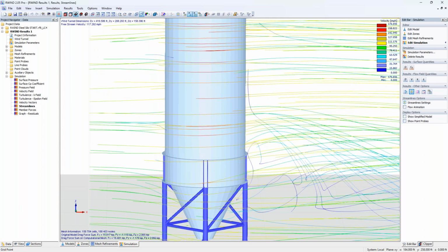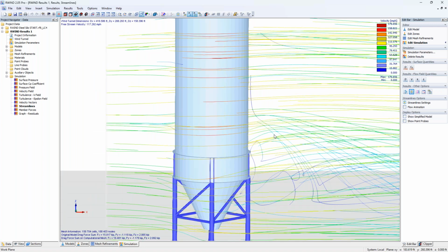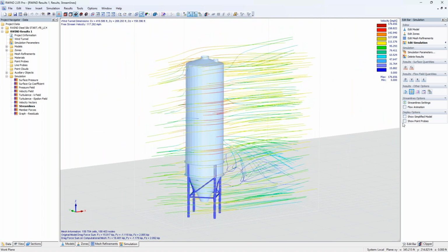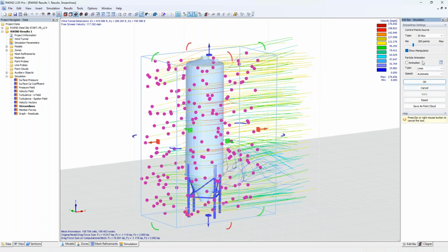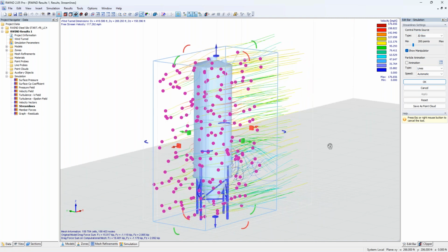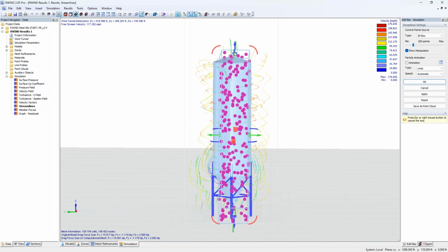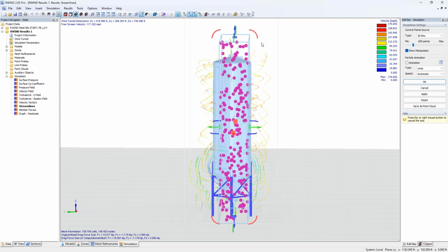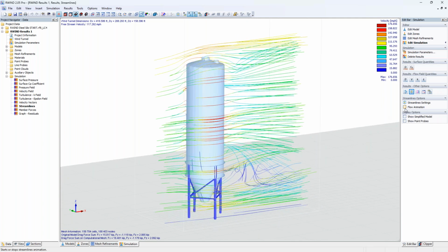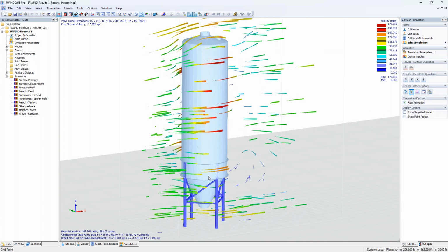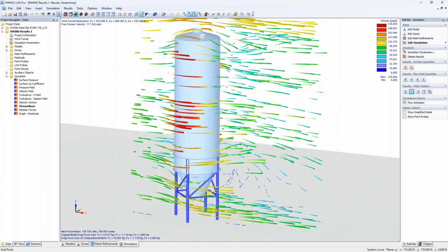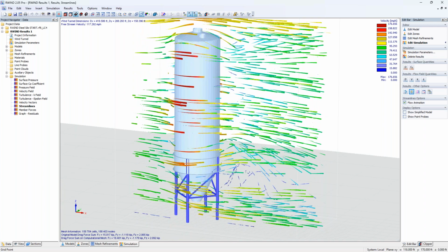So this is going to show the particles that allow me to study the airflow as it moves through this tunnel. And we can adjust the streamline settings here. And under the drop down up at the top, we can change this to a segment, to a rectangle, or currently we have it set to a 3D box. Additionally, we can rotate this around and graphically make modifications here to the size of our 3D box. If we wanted to set that to something more narrow, we could rotate it. Once we click OK, this will adjust those particles and we can activate the flow animation. So this is certainly something that's going to be helpful in studying those airflow particles as they move around our structure.